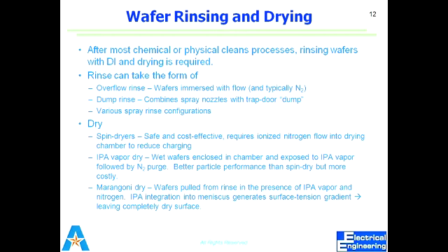In order to rinse the wafer and blow it dry with nitrogen, you don't do it manually. You have the dryer, which is the spin rinse dryer. You put the wafer inside, the DI water is sprayed on the wafer surface while it's rotating. After that, hot nitrogen is blown on the surface while it's rotating at high speed. Due to the rotation, the water splits up, so it makes the process even faster.